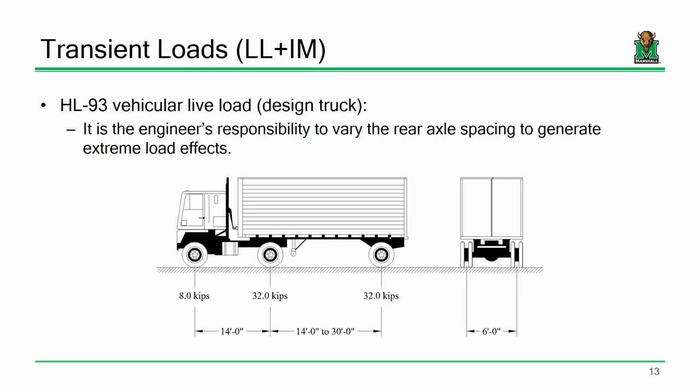But when you're getting into that level, like if you were actually doing a full-blown 3D computer model, AASHTO will tell you how to apply that load. It will say that this front wheel of 4 kips must be applied over a 10-inch by 20-inch area. That's the contact area. So you would calculate your pressure and then put that on your finite element model, if you're doing this 3-dimensionally. Okay. So far, so good?